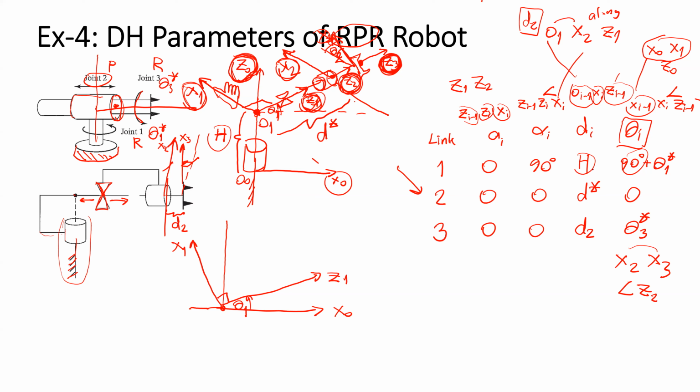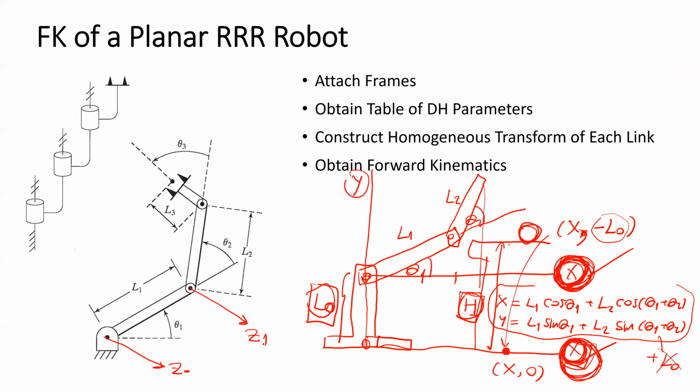And if we go back to this example, what you need to do is have the z-axis of C0, C1, and C2. For the end effector, you may try to have the z direction normal to the end effector and the x direction in the direction that the gripper moves.